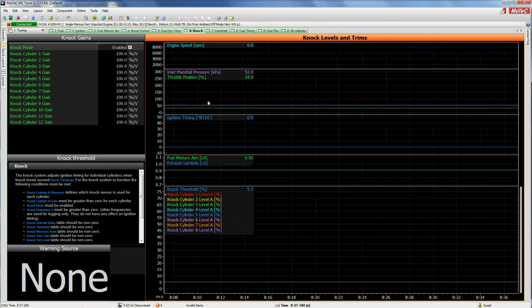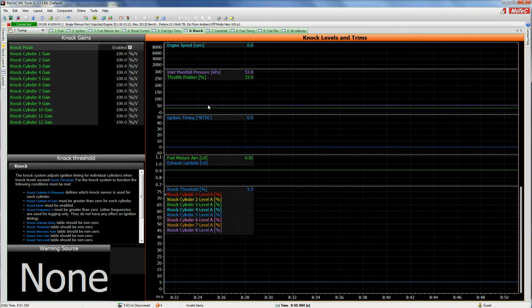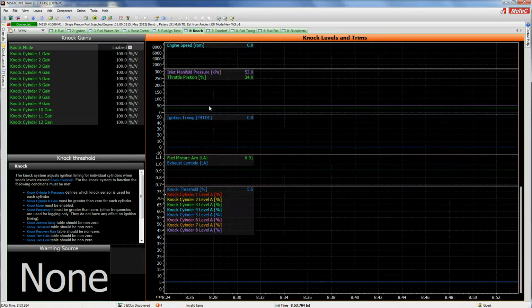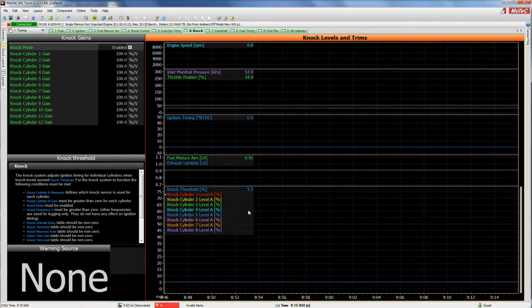And all the time while we're doing changes, we need to press Control S to save them to the current file. The ECU automatically updates instantly when you make a change, but if you disconnect from the ECU, shut the key off, pull the Ethernet cable out, you'll lose your changes in the ECU. You'll keep them on the laptop side, provided that you eventually push save, but you'll lose them in the ECU unless you physically force a save. So you can do it. It's not available now because I've just pressed save by clicking here, but laptop based we want to be using shortcuts, so Control S is the two keys to push.